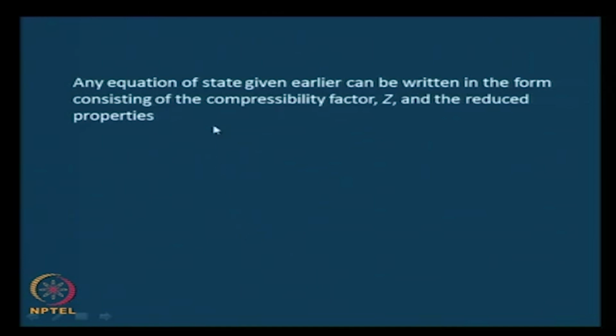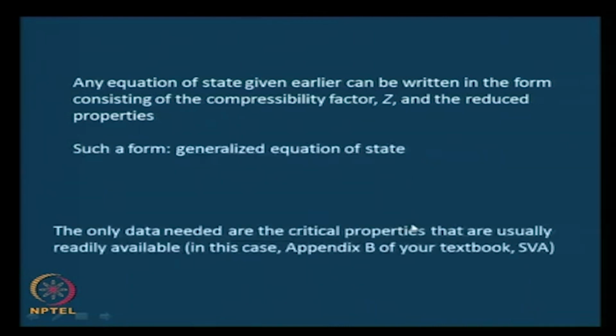Not just that, any equation of state can be written in terms of the reduced form or the generalized form if it is written in terms of the compressibility factor and reduced properties. And to re-emphasize, the only data that is needed when we use the generalized equation of state are the critical properties that are readily available, for example, in the appendix of your textbook.